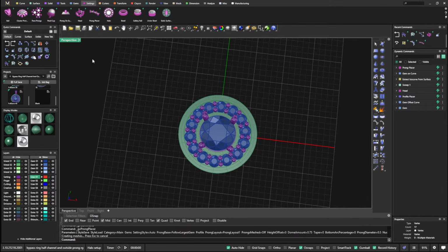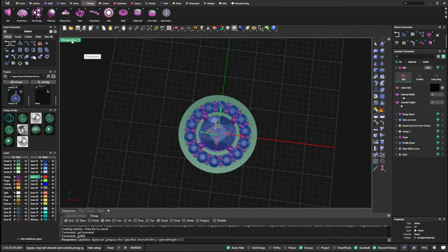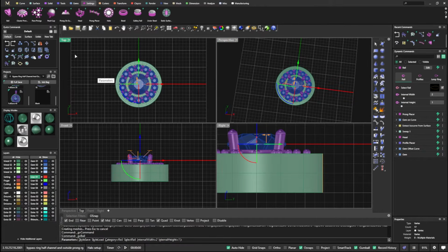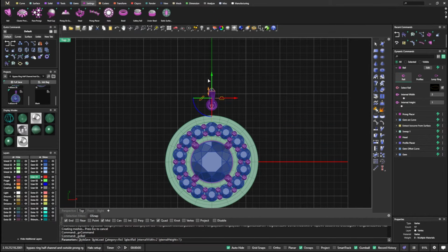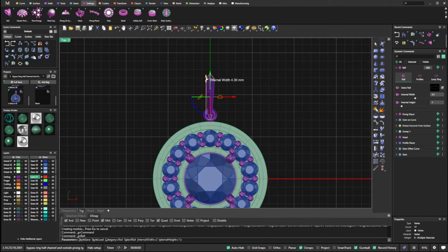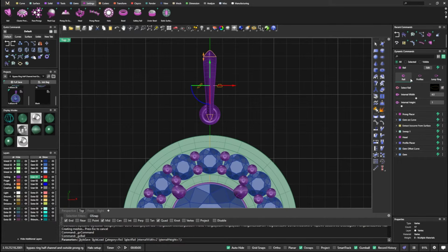One thing we probably want to go ahead and get taken care of is the bell, right? So we'll just go to our top view here for a few, and we'll just drag that bell out. And the first thing I'm going to do is get my bell in height. I'm going to say I want it around a 4mm bell. Let's make it a 4.5. How's that? Compromise. All right, and I'm going to drag that out a little bit because we don't need it touching at the moment. And the next thing I want to do is we have 3 little commands. We'll go into the bell and talk about all the commands and everything. That's pretty basic for the most part.